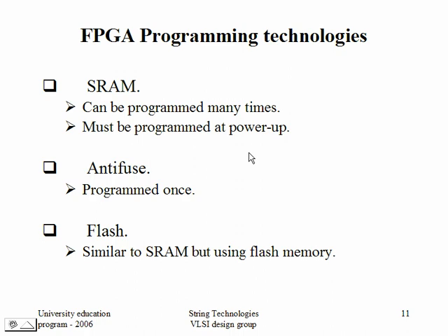Quite similar to that, even in all our fuse based concepts, CPLDs and FPGAs, wherever you say fuse technology, it is the same. Yesterday I also talked about PROM and the fuse. That's the same concept. There you have some kind of material which you blow by giving some amount of current, but not this large. Maybe 25 or 30 amperes I can blow the fuse. Exactly the same concept, but we use decoders so that we can route that current to the appropriate fuses where we want to blow, because we have so many fuses now.